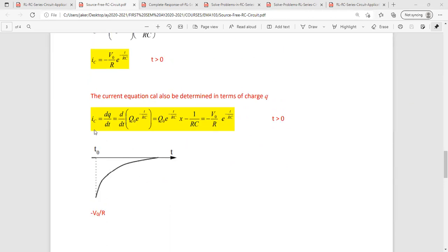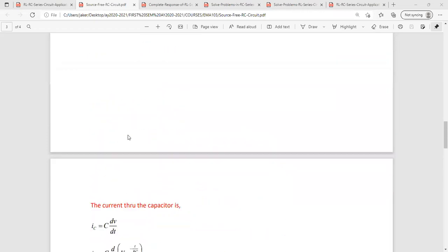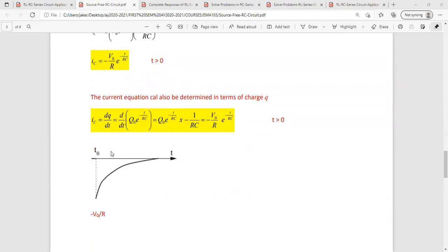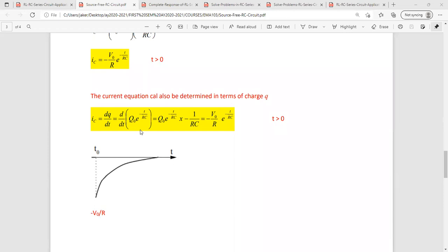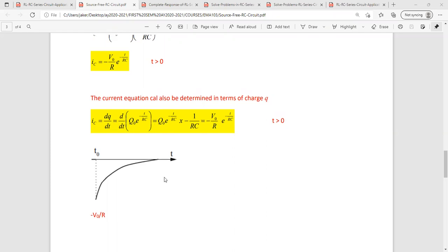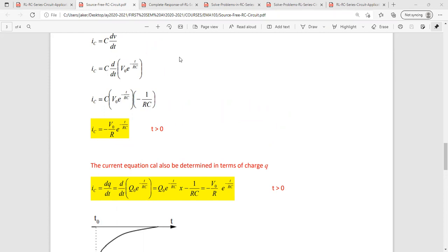Now you have here the current as well, if we change the Q expression in the derivative to the Q expression in here. So they are just substituted for each other. My suggestion is you should know the basic DE. You should know the relationships of the current to charge, and the charge to capacitance and voltage. Or so that you don't have to derive, you write down a summary of formulas for a particular case. So for a source-free RC circuit, I have my formulas. If it's not source-free, I start from the DE and differentiate to get what I need for the current.